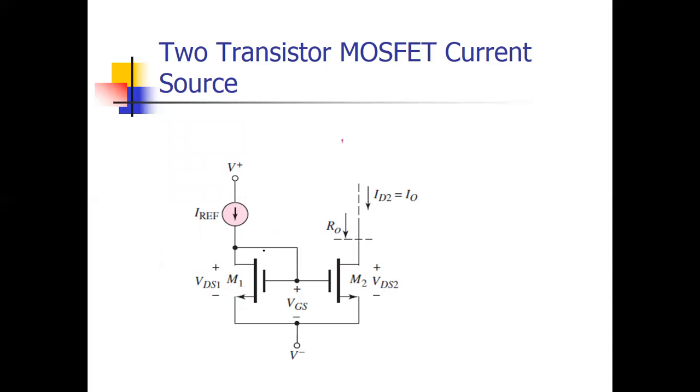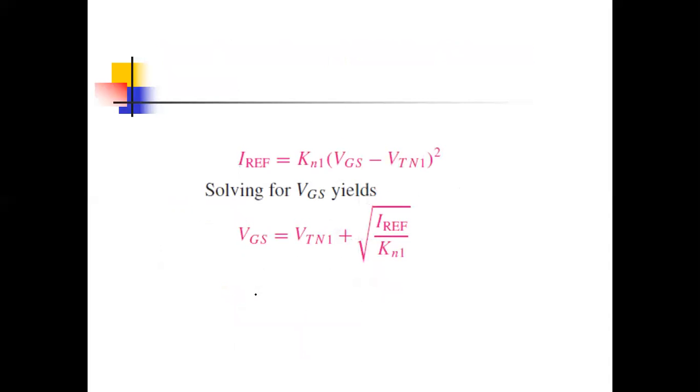Now it's a MOSFET and the equations of MOSFET are different. You can differentiate that it's an enhancement type MOSFET, not the depletion type. For an enhancement type MOSFET, if it is working as an amplifier, it works in the saturation region. In the saturation region, the formula of current is I equals K, where K is your device parameter. The value of K, if you remember, is mu COX into W by L. For NMOS, it is mu n, COX, W by L. Mu for mobility, COX for oxide capacitance, W is the width, L is the length.